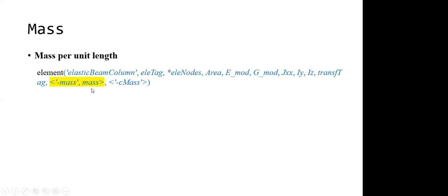Yes, when you use OpenSees, when it calculates it, it's actually lumping a mass at the end of the element as well. Okay, so that's how OpenSees does it. I mean, that's an important thing, because when we use this, we assume that it's actually calculating a distributed mass. So I just wanted to highlight that one.